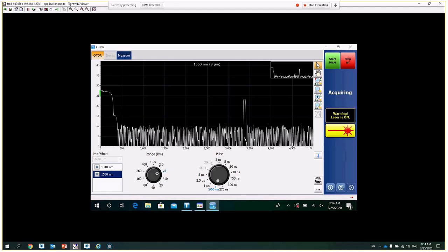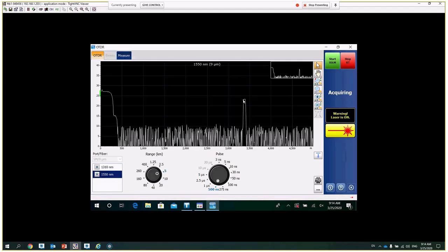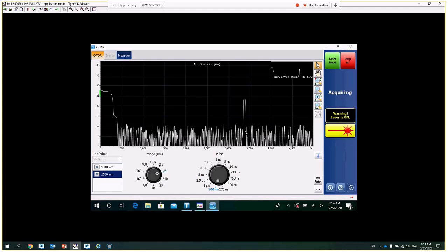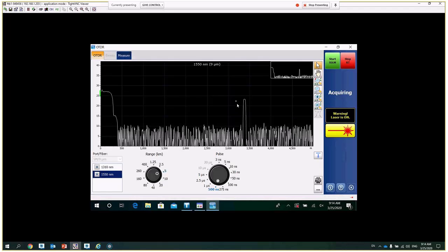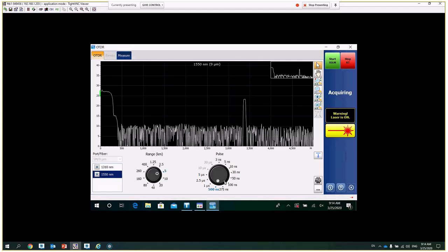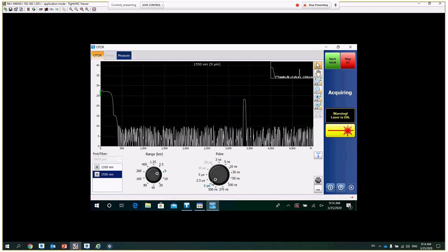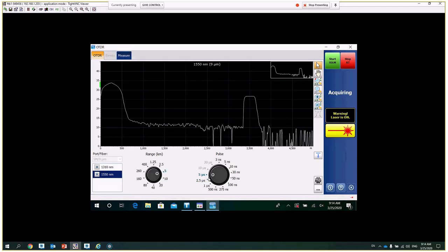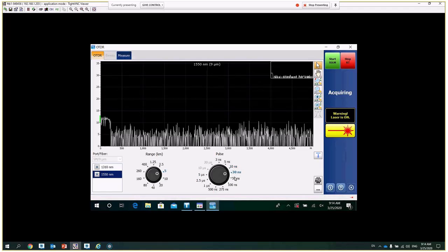For those of you that work with the OTDR, you will recognize this as a UPC connector due to the reflectance, and that's why you may have UPC or APC on your network. The UPC, because it's a flat cut on the connector, always has these high reflectance peaks, which are not seen on the green APC connectors. If you go above, you can start seeing the end of the fiber. So different pulses, different settings will always give you different measurements.